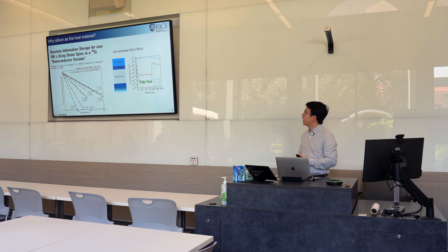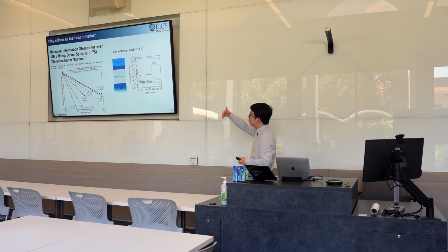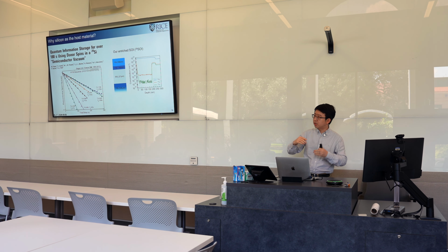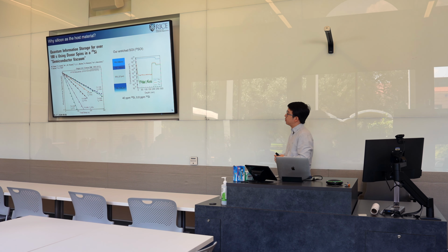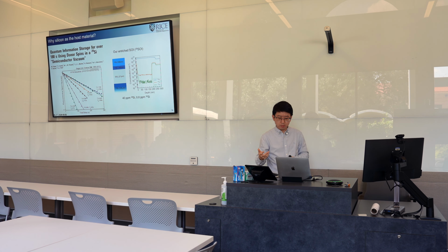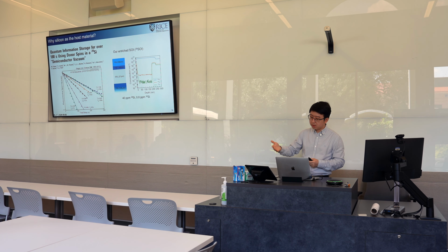So in our group, we have developed this material stack where we start with a commercial SOI wafer. We polish down first, and then we regrow enriched silicon-28. And then we can confirm from this mass spectroscopy measurement that in this piece of material on the top, the device layer, the silicon-29 is now 40 ppm. So ppm is parts per million, right? So 40 ppm is, instead of 5%, now 4 times 10 to the minus 5, okay?